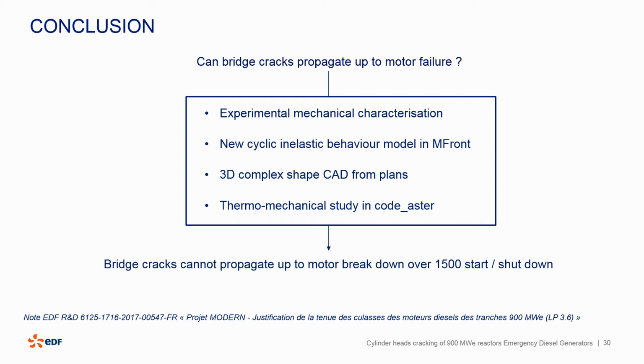So internally we made the same mesh, the mesh without the crack, and then we buy this software called ZCracks, which is an interface inside of the solver, but you need a license in order to use it. What it does is that you independently mesh the crack, so the surface of the crack, and then this software makes the junction of these two and produces a new mesh that will be different. It uses tetrahedral elements because it's easier to mesh, of course, but it can keep boundaries that already exist.